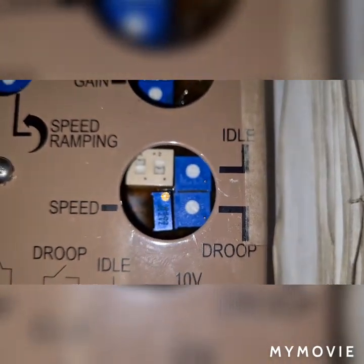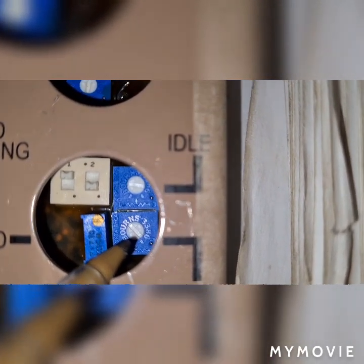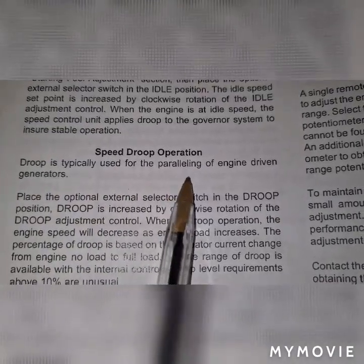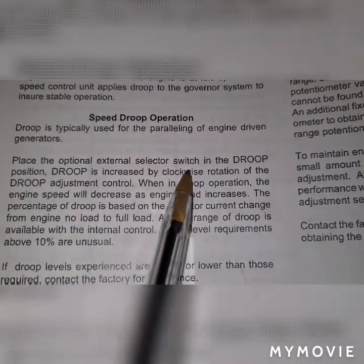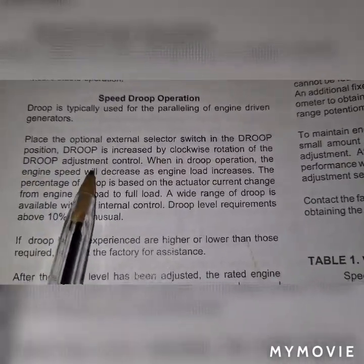We have also here one potentiometer known as droop, labeled Bourns 3386. Speed droop operation is typically used for paralleling of engine-driven generators. Place the optional external selector switch in the droop position. Droop is increased by clockwise rotation of the droop adjustment control.